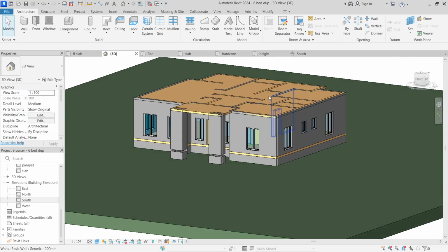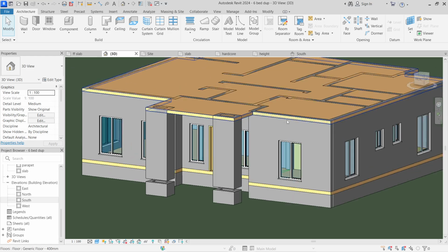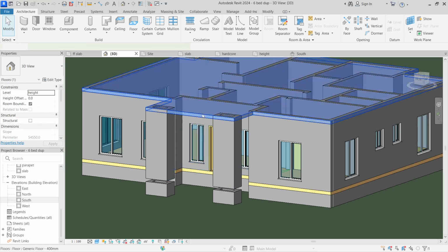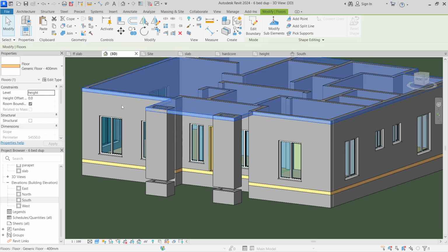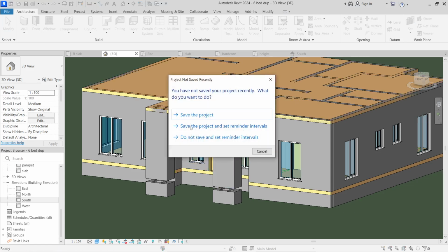You see, on our 3D, we are able to achieve this. So look at the way our slab, our first floor slab, is penetrating through our block, which is not normal. All we have to do is to take it up to our first floor slab. It will be okay, or we add. Let's select it. Either we add the thickness of our slab, which is adding 150 at this point. When you add 150 at this point, now it is okay. Understand?